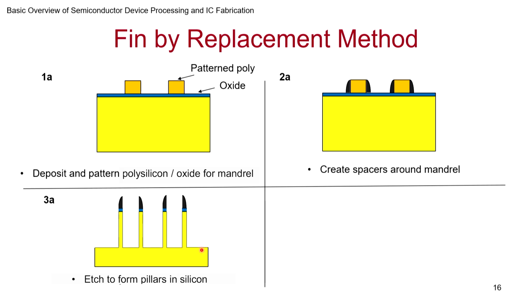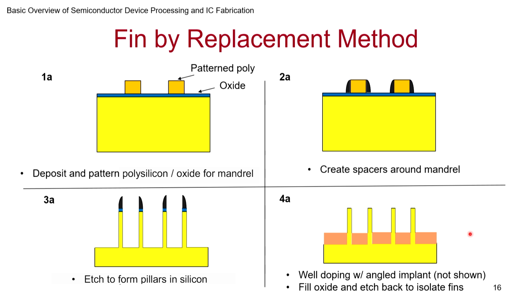Do you see the advantage of all these various processes? You bring in something where nobody would have thought that it would play a role, and you are able to get a very interesting structure. So using these spacers as the hard mask, you do this. Then of course you can remove the spacer. You do the implant as before for the well structure. It's very similar now.